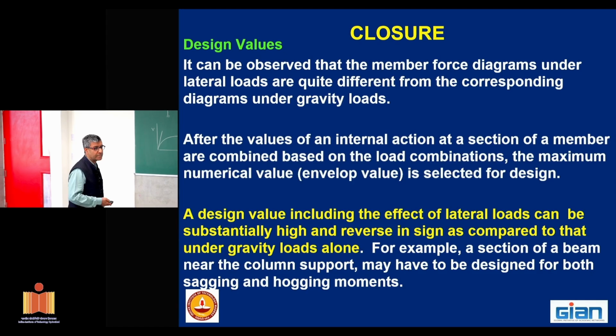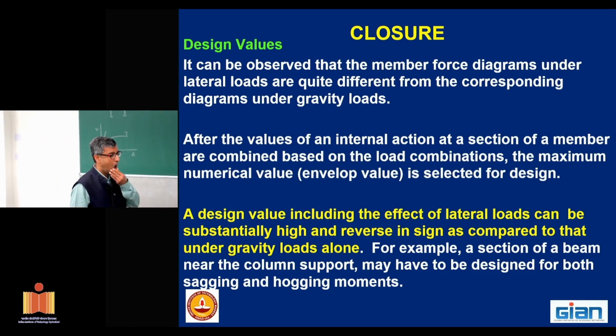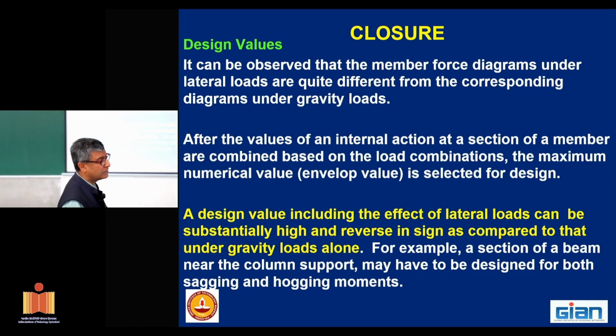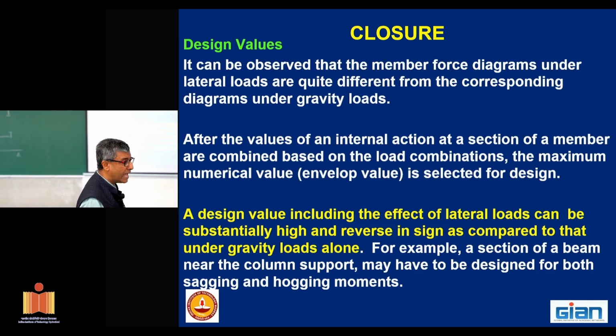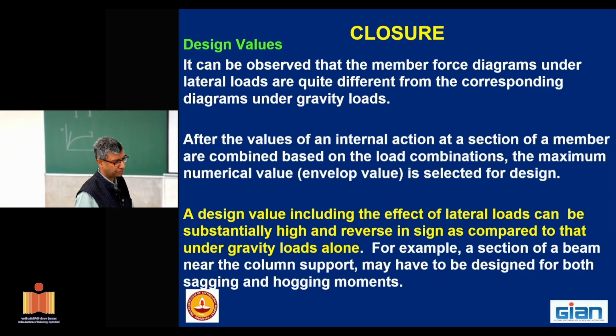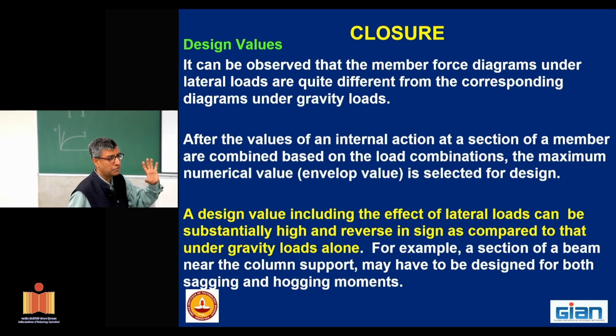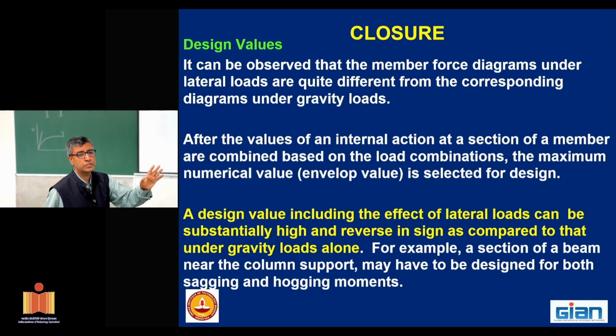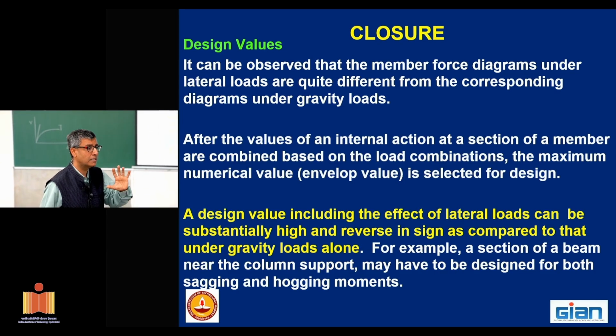So if I'm a construction manager, I ask my contractor to provide me both lateral loads and gravity loads, right? Yes, separately. I will ask my contractor to make sure he provides me diagrams under lateral loads and under gravity. I would say as a proof checker or plan checker, that's the way I would do. At first you show me the force diagrams under gravity load, force diagrams under lateral load, and then show me the envelope diagrams under the combined loads, so that I understand what the modeler has done.